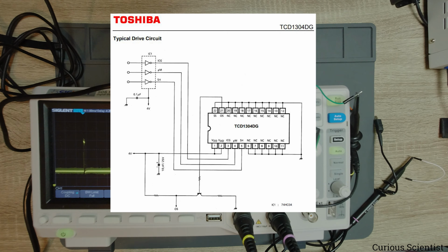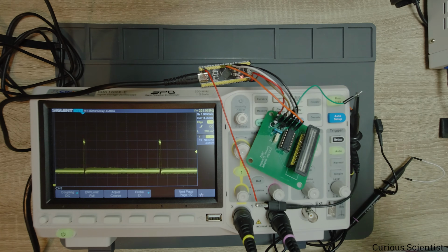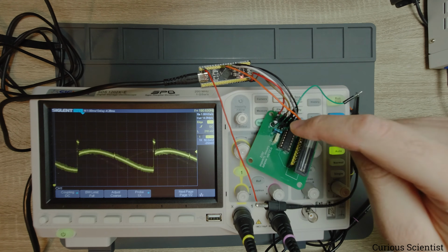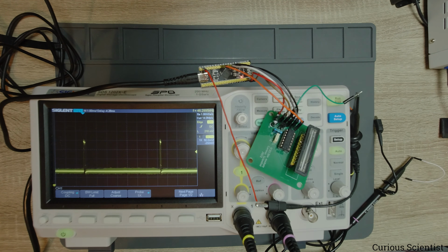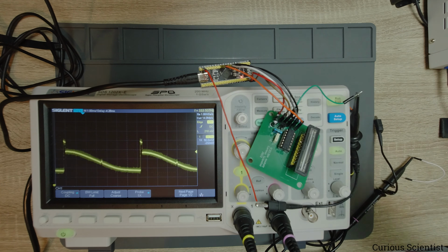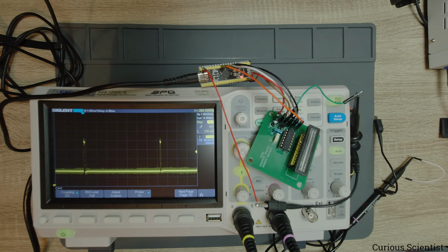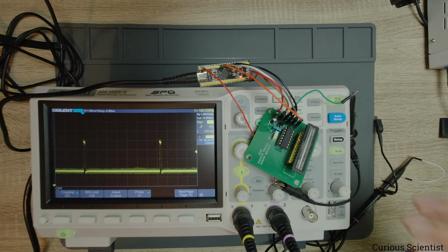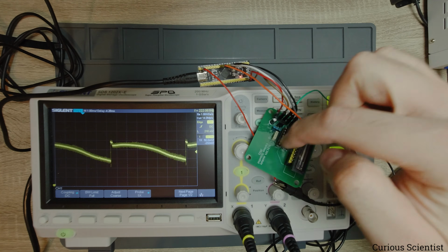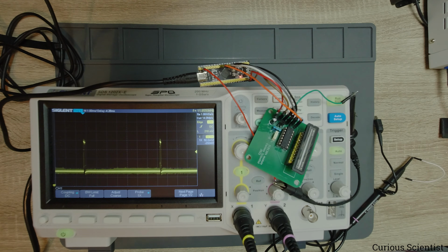So I just copied that circuit, and then I used KiCad, drew a very simple schematic and not so well designed PCB, because of course this electronically could be improved, so we could have less noise, but it's enough to drive the CCD. So as you can see, the whole custom circuit is located on a PCB. So here's the CCD and some circuit which serves the CCD.